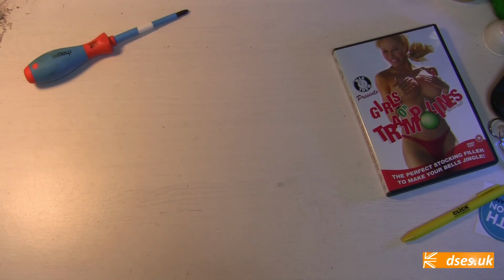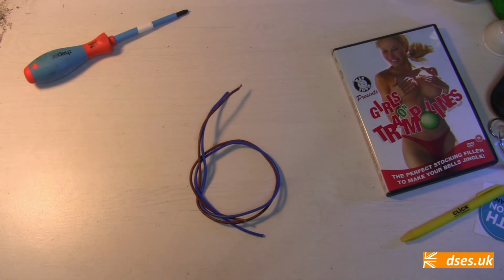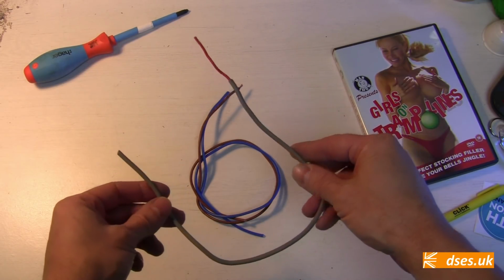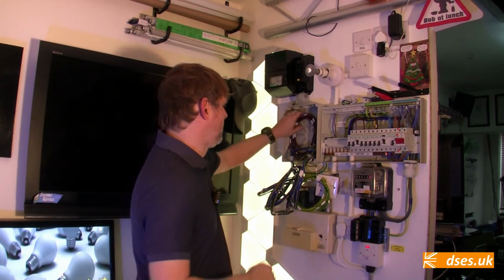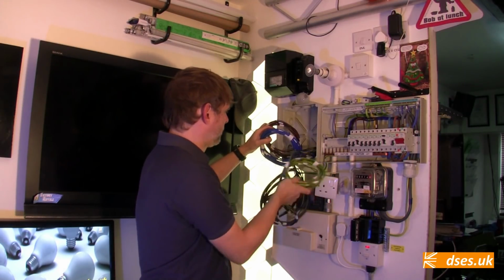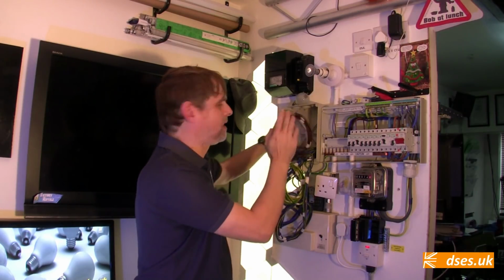Of course, singles, as found in conduit wiring or in its double insulated form on older UK installations, are a different kettle of fish and can potentially see line and neutral snaking around the building separate to each other, which isn't ideal. And to see why, here I have separated line, neutral and CPC